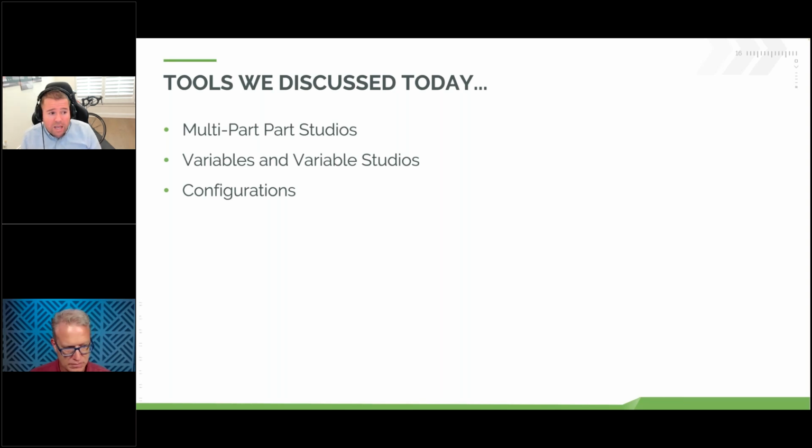So if you're in that camp, you know it, and a lot of this stuff hopefully is good practice for you to take into your next design. If I had to point to really one power user level function that is really useful for building robust designs, it's expressions, because they allow you to build those relationships really quickly and easily, and make the design much more flexible to change. You can really build a model that changes based on a handful of factors and updates thousands of dimensions in theory. So you can really do some powerful stuff with expressions.